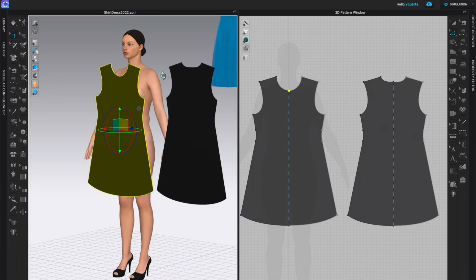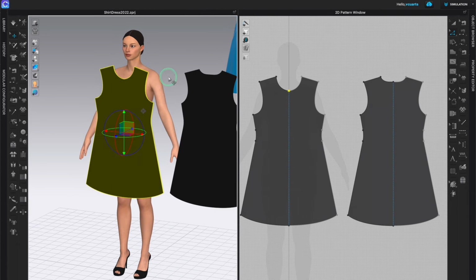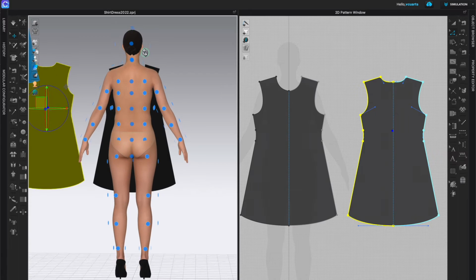So I can manually do that with all of my pattern pieces, or I can get my arrangement points. And remember, this is in the vertical toggle menu by the avatar display. The second one in, that's arrangement points, or Shift F. And by using arrangement points, it allows you to quickly place items.